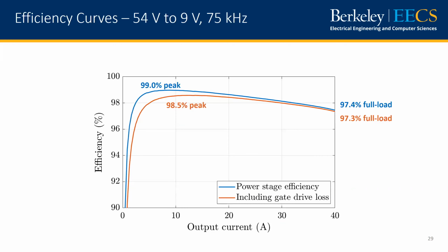So, yeah, we have a couple of questions. Sure. Ceramic capacitors are being used here, so their value might change due to voltage bias. So the resonant frequency can also change. So how are you dealing with this effect?